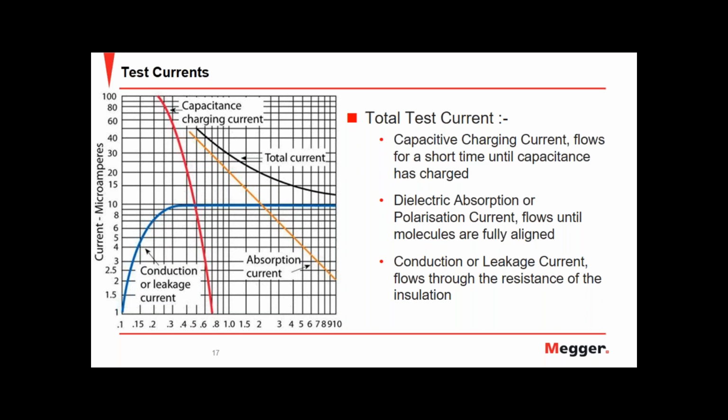So I don't think it's an issue if you put the negative on the HV guard and the LV on the positive or on the ground. It shouldn't have really an effect on that type of instrument. It was a carryover from older cable type designs. So the answer, in a nutshell, is no, it shouldn't be an issue.